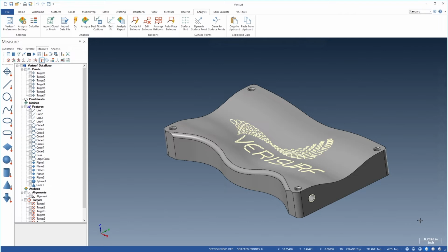We can change the graphics view using the keyboard or the mouse. The arrow keys move the viewport, causing the image to move in the opposite direction. If we press the left arrow, the model moves right and vice versa. The up-down arrows work in a similar way.